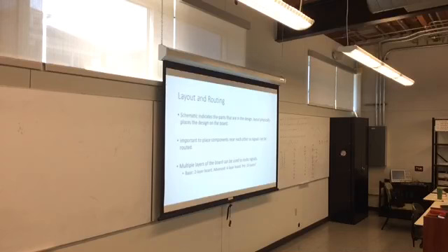Right, so the more layers that you've got, it's like the more lanes on a highway. You've got more space to send people. Like you can send more traffic through more easily. If you've got a 2-layer board, generally they make a bottom layer ground, because everything's got a ground connection. But then that leaves one layer where you have to route all of your signals and all of your power. And these lines cannot intersect because they're all on the same layer. It's like playing Snake. Like you can't move back and hit yourself.